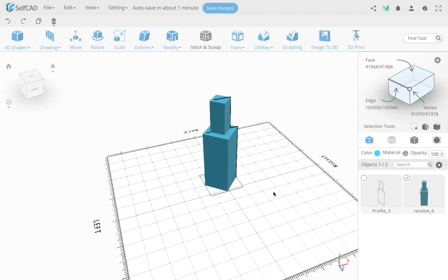So again, Revolve is a function that rotates around. It takes the outside edges of the shape that you draw, and that gets rotated around. So you always have to duplicate that, plus the inside emptiness, plus the other side, but you can play around with this. In the new SelfCAD update, you also have an option to choose Revolve Around Edge, which adds a lot more flexibility, but that also requires more expertise. For basic use cases, that should still be the same. There will just be another option, Revolve Around Edge, mainly for more advanced things.